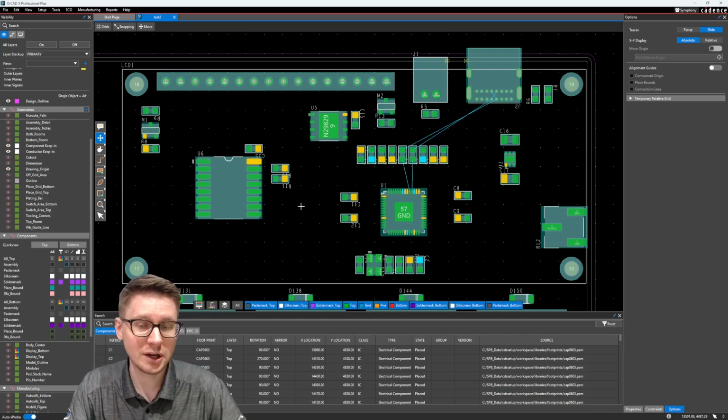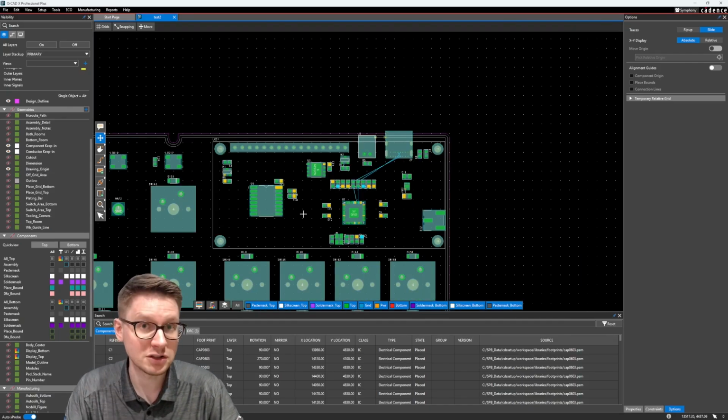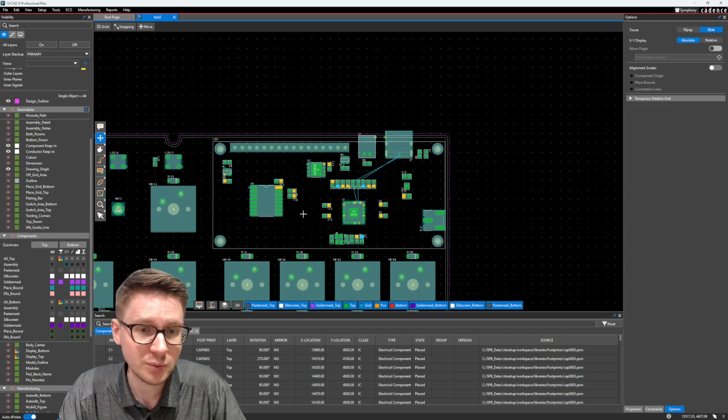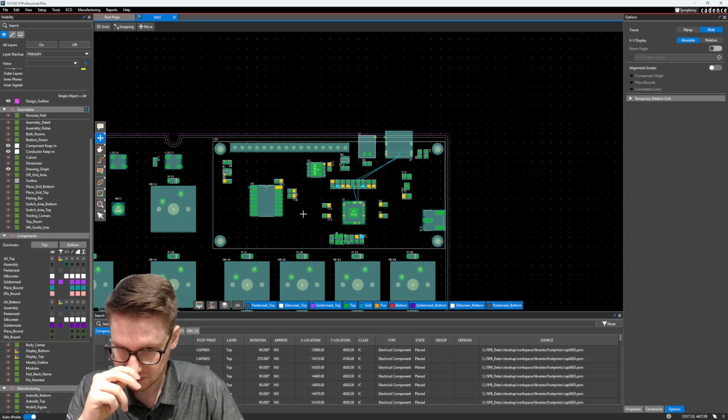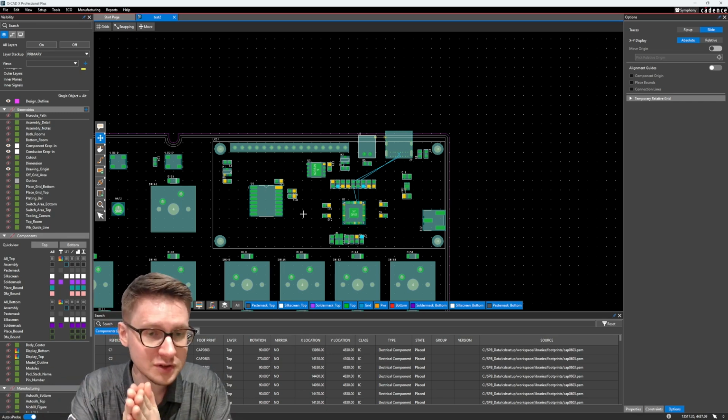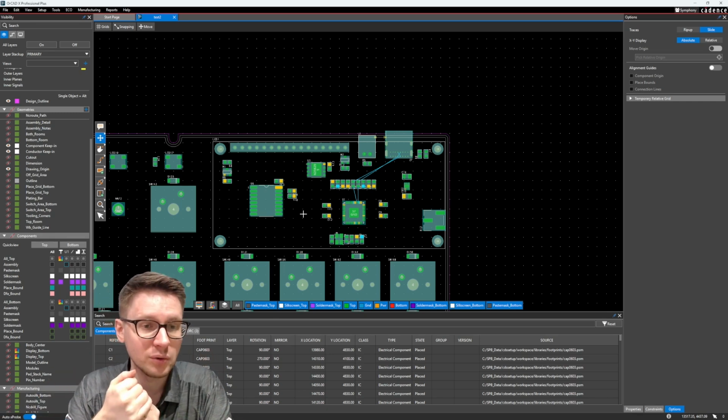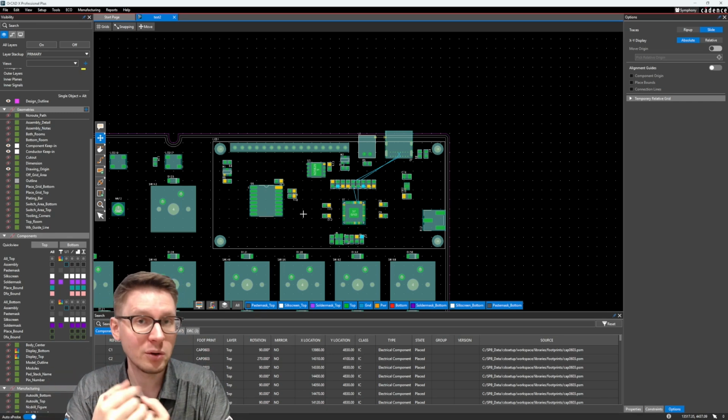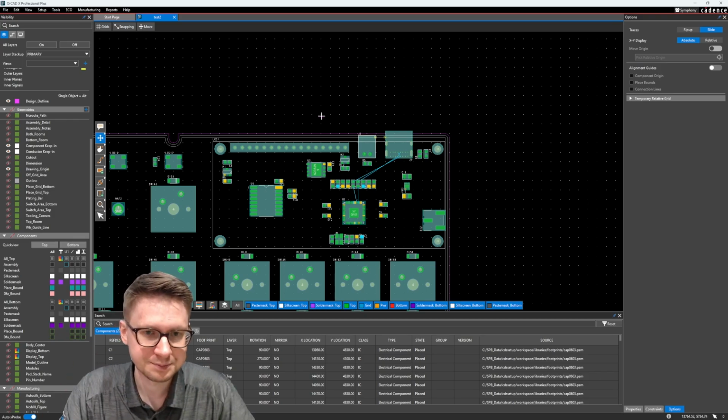section of the design, right? As this is kind of the most touchy section of the design. And this is just to make sure that our board is manufacturable, to make sure that we are not going to be placing traces too close together, making sure that we're using the right via throughout our design, and making sure that our power traces also have a slightly thicker trace width.